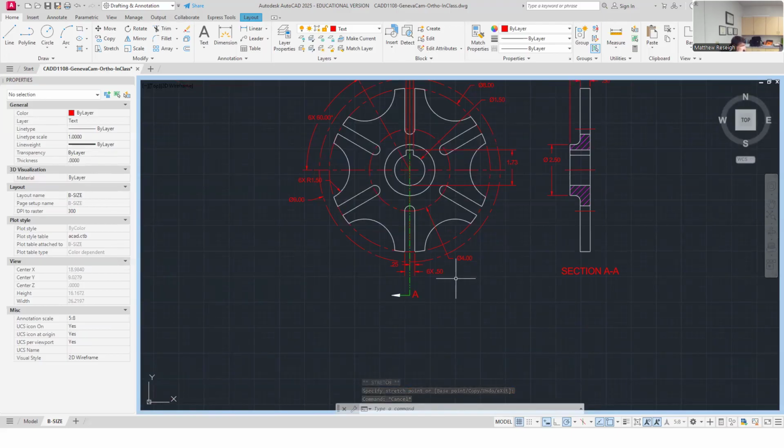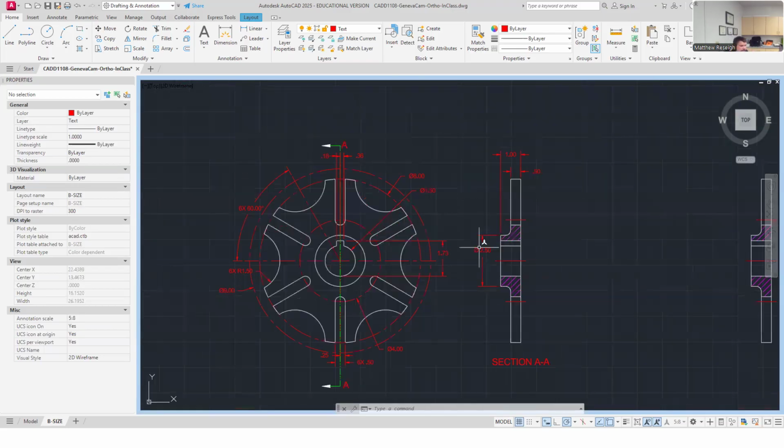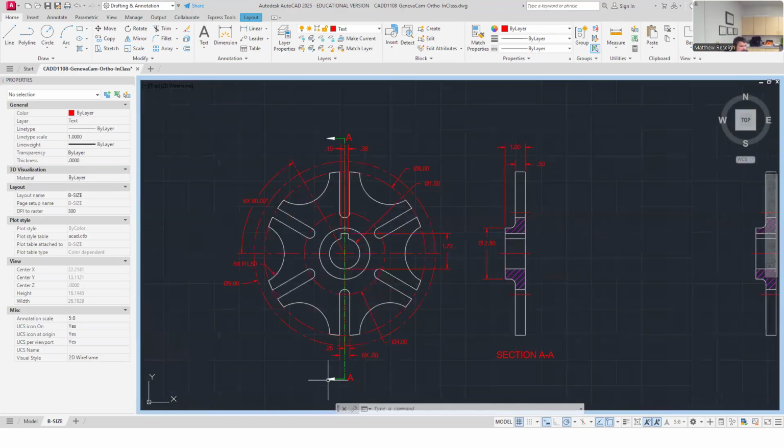It becomes more of your life in mechanical drafting that you do. In order to really truly dimension stuff correctly, it's probably got to become sectioned or detailed out a little bit bigger. A detail is just where I can almost zoom in and then do an additional scale up of some feature. Like I could zoom into this keyway and just break out a section of it and do a detail view of that keyway. And so we haven't done any of those yet. This is our first section view, so I'll just keep it like that.